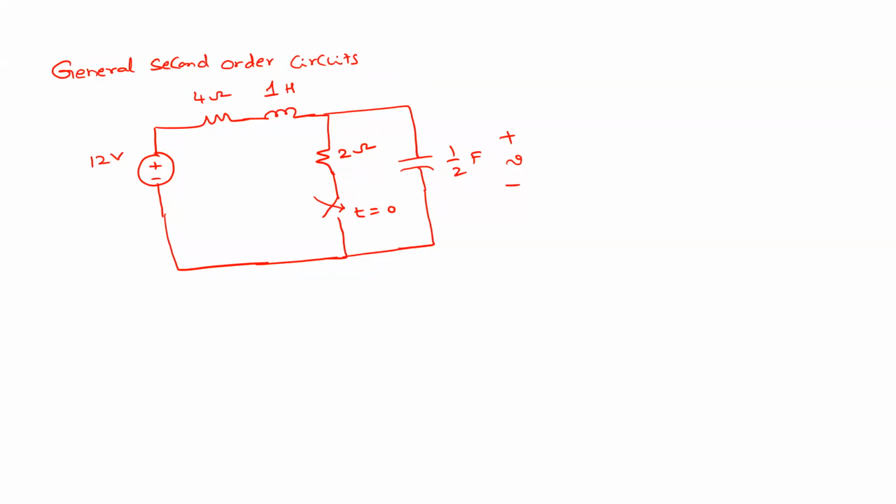So if you notice, when this switch is closed at t equal to 0, this circuit is neither a series RLC circuit nor a parallel RLC circuit, right? For this kind of problem, some may think that we can convert this into its equivalent current source. Is it possible? No, sir. Because of this inductance. If it were an AC source, then it would be possible. If this inductor is not present, you may convert this into its equivalent current source.